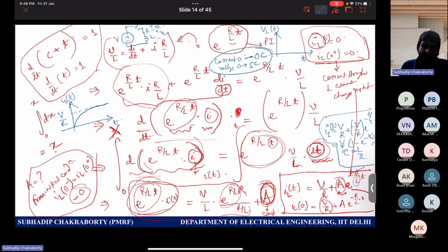So the voltage across inductor, what will it be? V. Yes, V. Complete voltage will be impressed upon the inductor because it is open circuit. And the remaining part of the circuit you just analyze. No current flows, so no voltage drop across the resistor. And this complete voltage appears across this node. So the voltage across inductor is V.